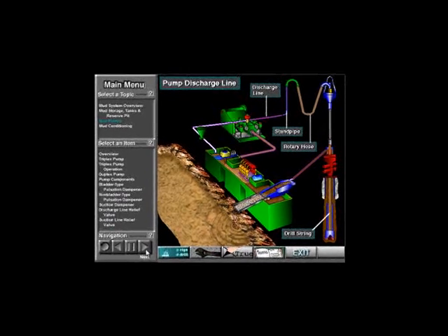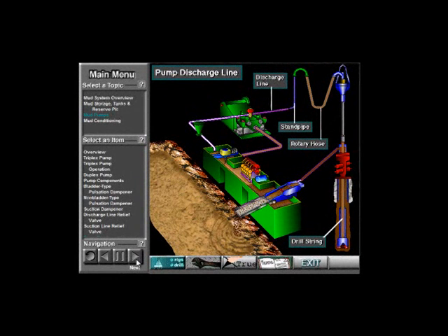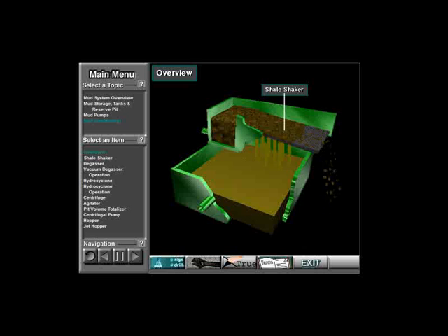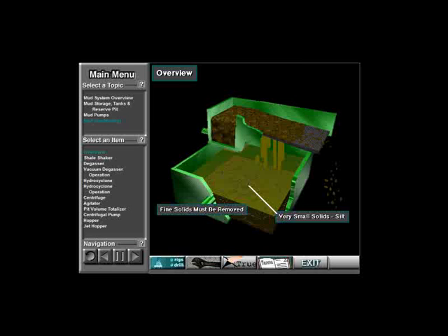Discharge line, the mud goes through the standpipe and rotary hose to the drill string equipment. The shale shaker mechanically takes out the large cuttings from the mud. It does not, however, remove very fine cuttings and other small solid particles. These solids can be fine sand particles and other very fine materials, often called silt. Good drilling practice requires removing these undesirable solids.